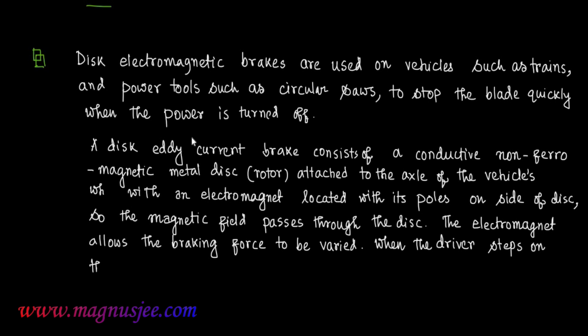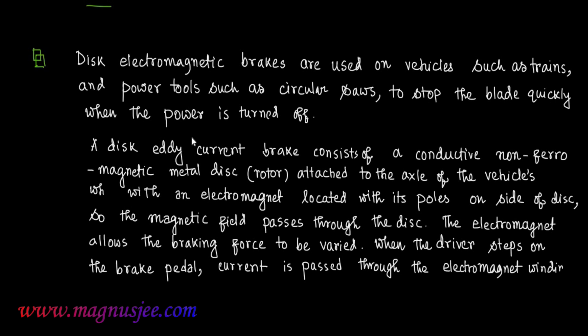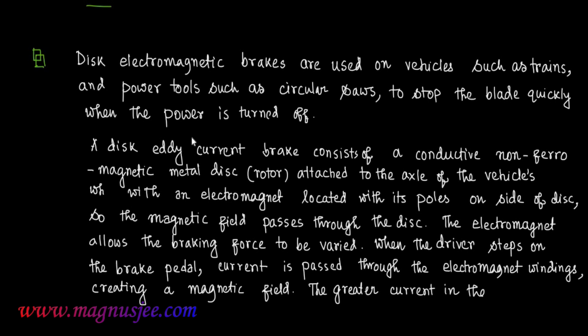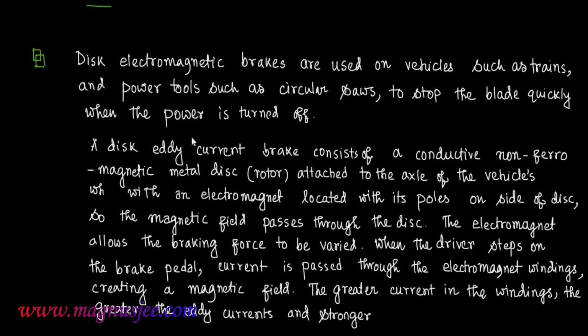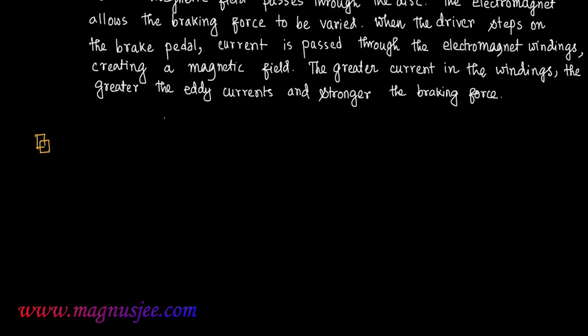When the driver steps on the brake pedal, current is passed through the electromagnet windings, creating a magnetic field. The greater the current in the windings, the greater the eddy currents and the stronger the braking force.